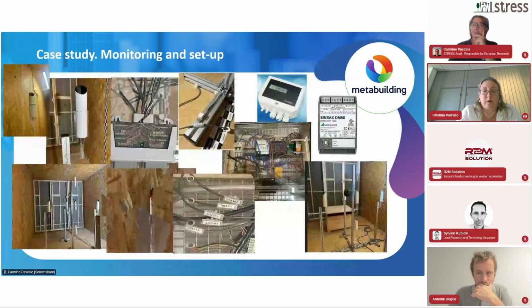And also we would like to have a very good homogeneity in the temperature gradient inside the cell. So we have included the PT100 temperature sensor, fit in this system that you see like a white tube, because we try to prevent the effect of the radiation, and that also allowed us to have different points and heights to situate within the cell.